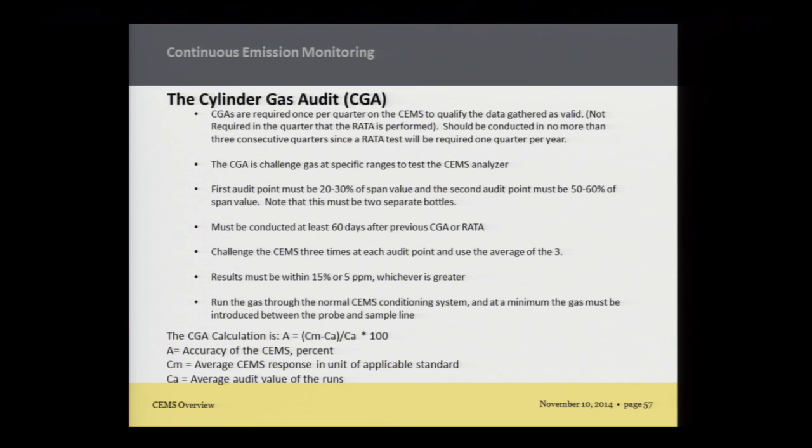So if you've got a heater that's not applicable to a MACT or an NSPS that requires a RATA, you can run 4 CGAs. But here's where they caught it. The EPA kind of found that recently, and what they did is with the heater and boiler MACT, they make you go do a RATA. So up until heater and boiler MACT, if you just had a heater that had a CEMS and there was no federal driver, the state just said you're greater than 100 million BTU in Texas, and you've got to put a CEMS on. You didn't have to do a RATA, and even in the permits it would say you could do 4 consecutive CGAs, so just a little cost savings. But by getting applicable to the heater and boiler MACT, now they've dragged pretty much all the sources in, in that if you've got a CEMS, it requires you to run a RATA.